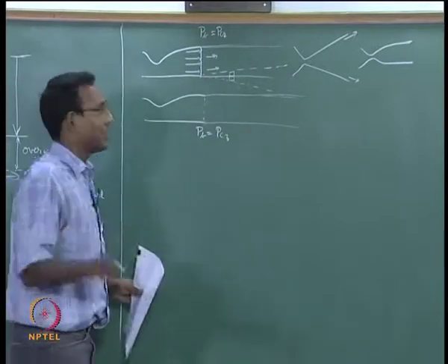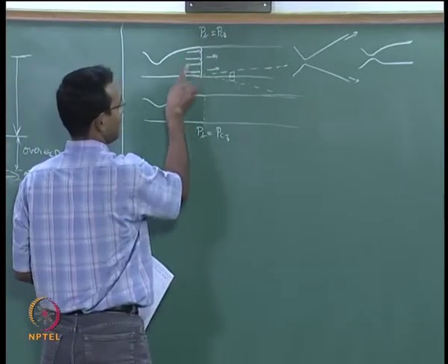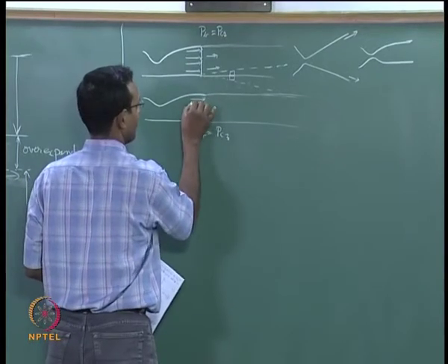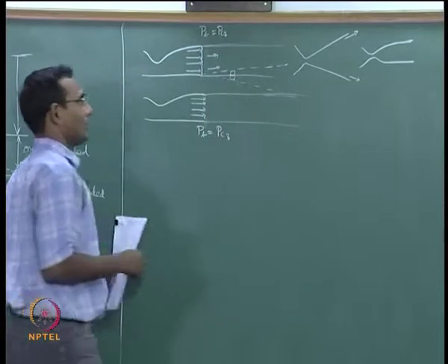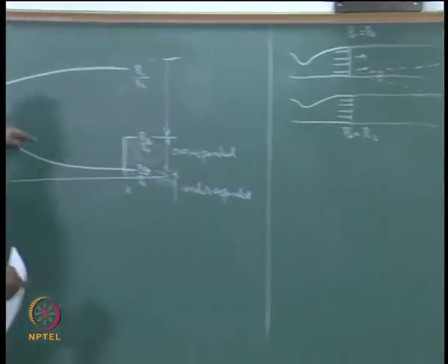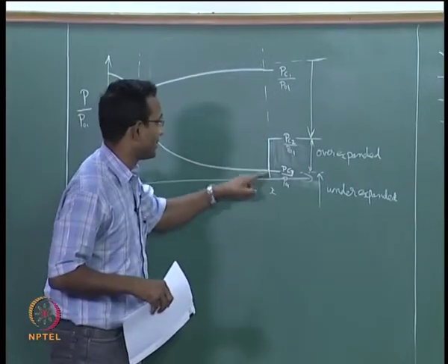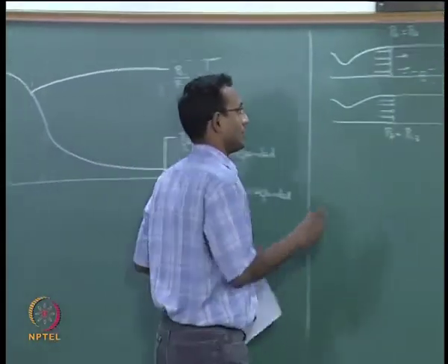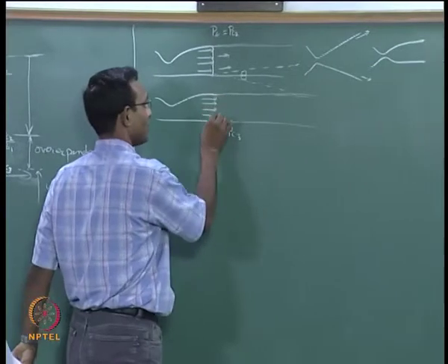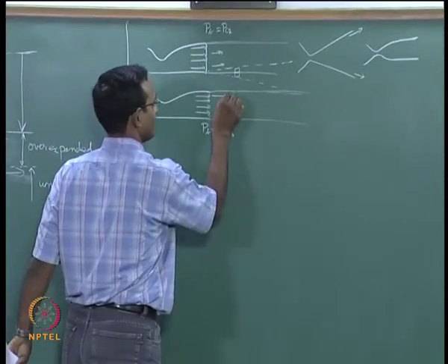The only difference now will be whatever is the velocity here at the exit, it will be the same value here. Why is it the same value? I go back to this curve and I see there is no change between PC2 and PC3 up to the exit, it will be the same here. So, I am going to say, and there is no shock at the exit this time, it will be the same on the other side.